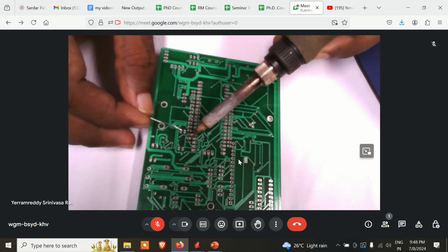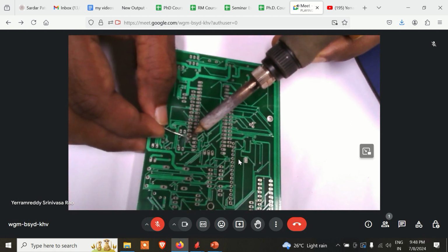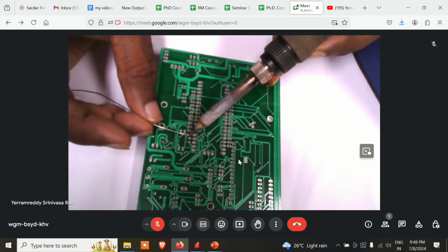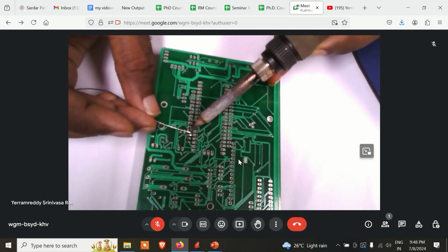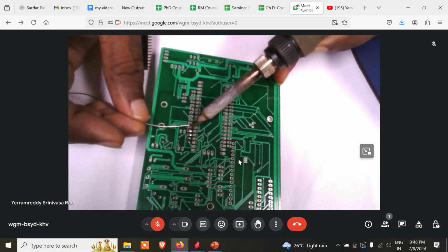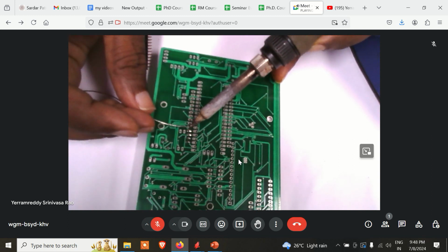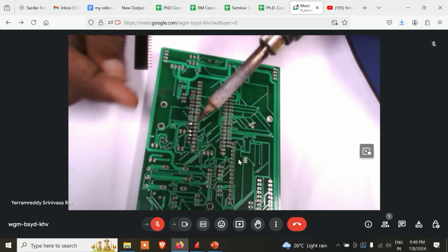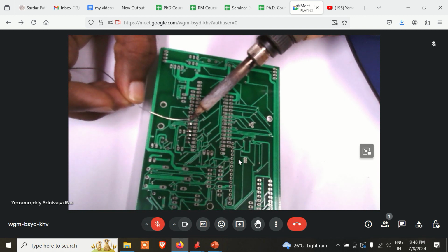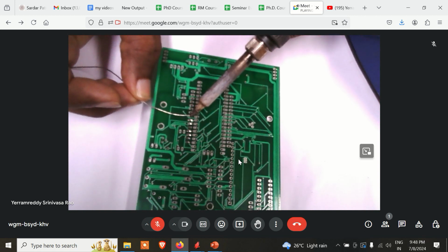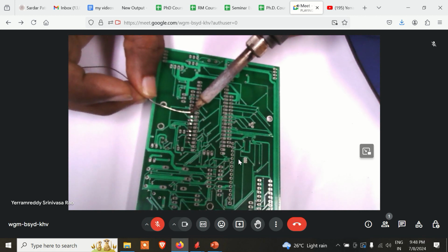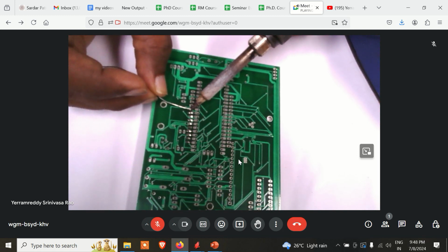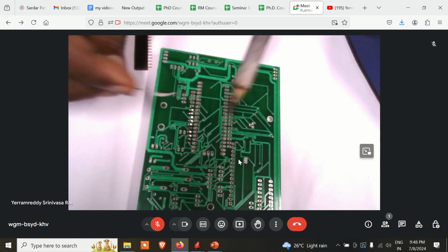Place the gun and the metal together on the pad at 45 degrees, melt it on the pad, heat the pad. The solder should look uniform. Solder should be only on the pad, all four sides in the liquid state, so heat it for a fraction of a second so that it flows over the entire pad and does not short the neighboring pads. Do not use excess metal.